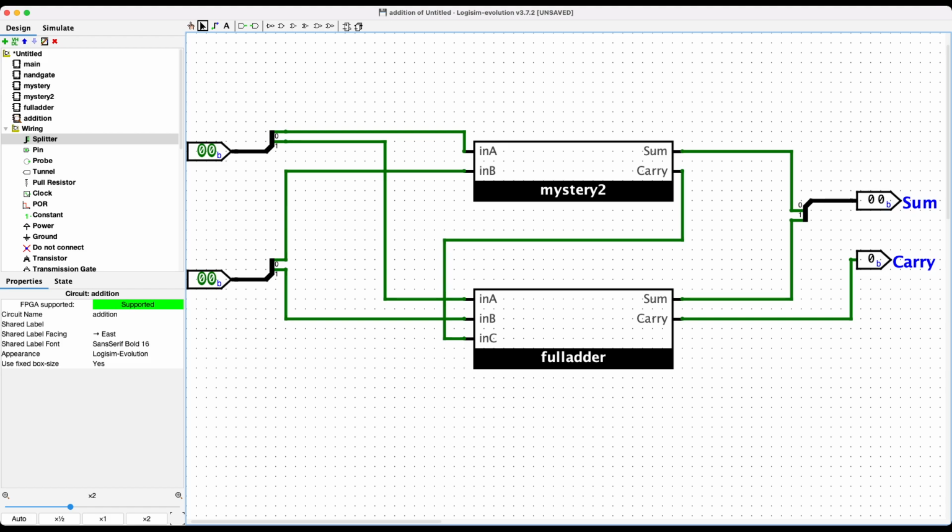Now think about it this way. We've got 4 different addition instructions there. Should we build 4 different addition units in our processor? No, that's a monumentally bad idea. Why build 4 of them when you could build 1 and use it 4 different ways? So that answers that question. There's only 1 addition unit. So in a modern computer, there would not ever be a half adder in the addition circuit.